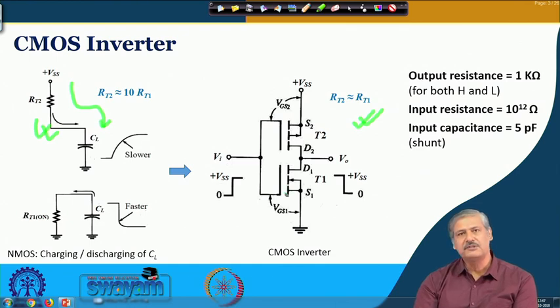While in NMOS, when we look at the working of the NMOS, basically you are placing a positive voltage above a threshold voltage, which attracts electrons, and an N channel is formed, okay, and the current conducts. In case of PMOS, what will happen? We want to form a channel made up of holes. So, a relatively negative voltage needs to be applied.